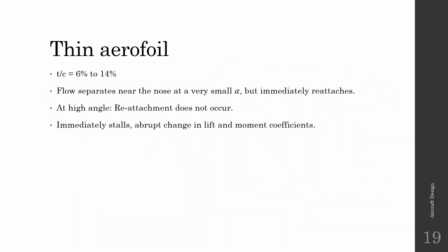The next class of aerofoil is thin aerofoil. Over here your thickness to chord ratio is between 6 to 14%, and over here the flow separates near the nose at very small alpha, but it immediately reattaches. And at high angle of attack, reattachment does not occur, and this causes an immediate stall and abrupt change in